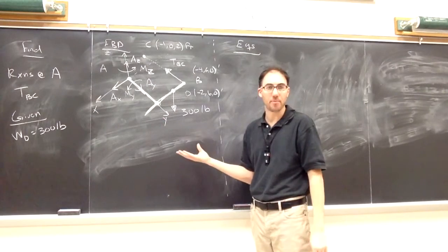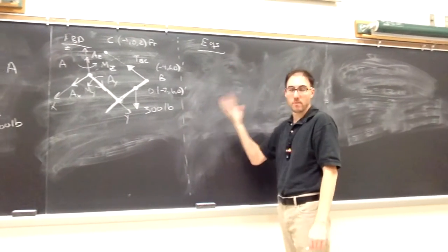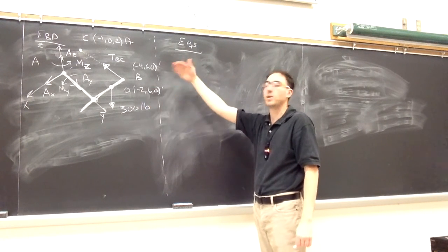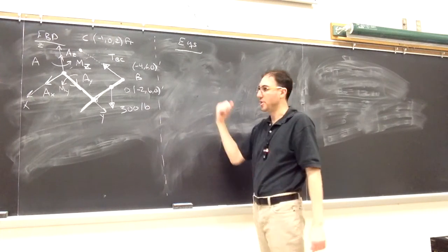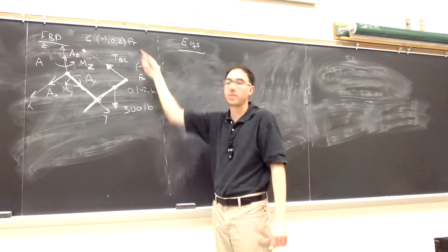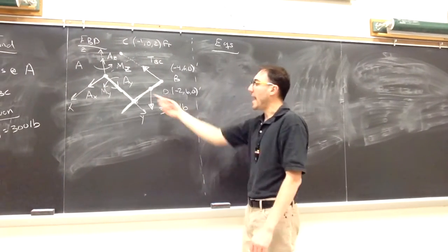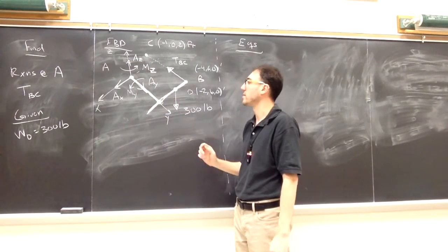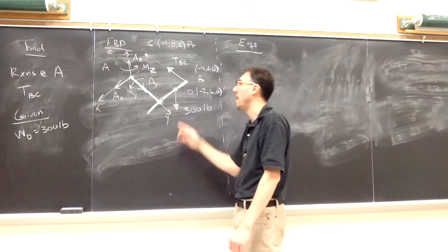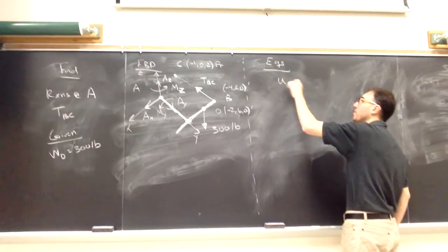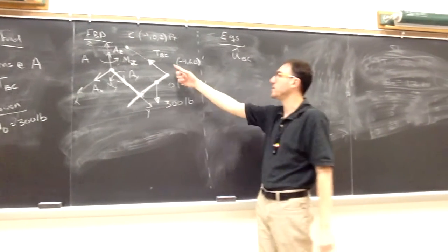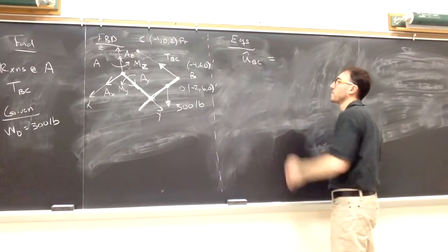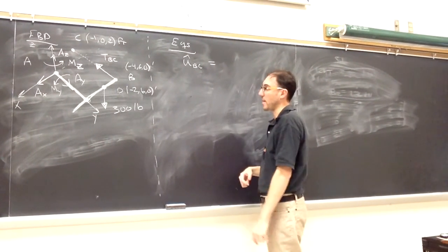And I would have known it's incomplete right away because the first thing, or what I suggest the first thing you do for the equation step, before we write our equilibrium equations, what should we find first? Right, the unit vectors, and to find unit vectors, these coordinates we are going to need. AY, AX, AZ only act along X, Y, and Z, so those are fine. The weight only acts along Z, so that we don't have to worry about. What we want to find is the unit vector from B to C, so that we know how much of the tension is along X, Y, and along Z. And that'll make the equilibrium equations easier to write.